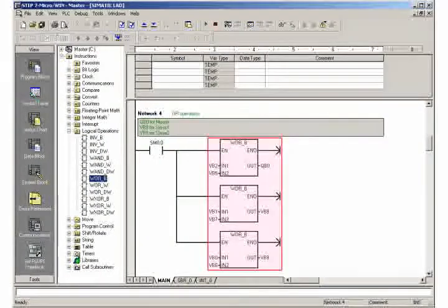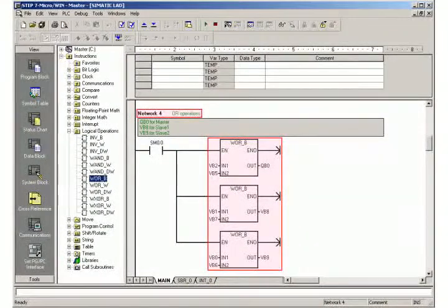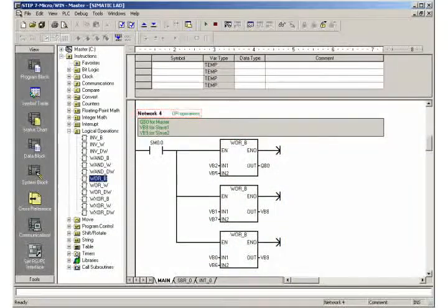Byte by byte, logic OR connections of rising and falling running lights per PLC occur in network 4. For the master, the result is directly output to QB0, and for the slaves it is intermediately stored in the memory byte 8 or byte 9.